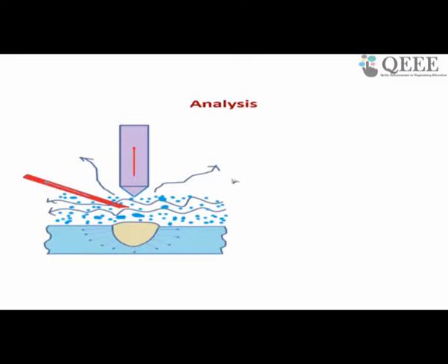Then in today's class we discussed resistance welding. In resistance welding, what we understood is that you can join only thin pieces, but it is a very quick process. It can be automated, and largely this process is used in the automotive sector. We discussed that the heat source is Joule heating, I square R. So that we finished. Now we'll discuss solid state welding processes.